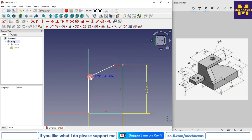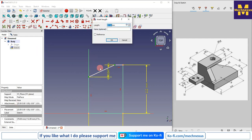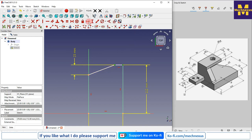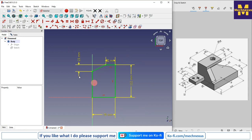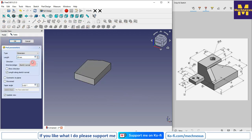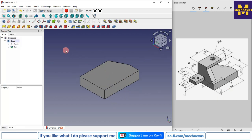And we will move this point and this point to this point is a 23, and this point to this point is a 32. Click on close, and now we will create the pad of 25 mm. Click on the pad and give the 25, switch to the isometric.